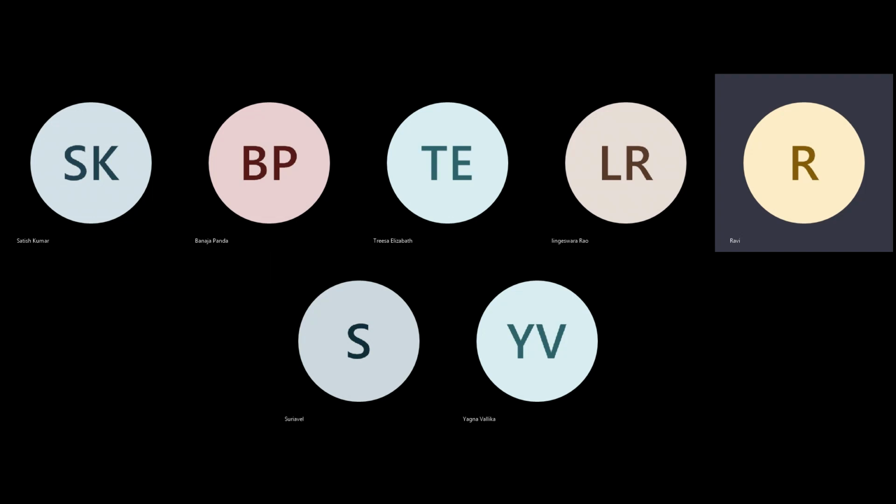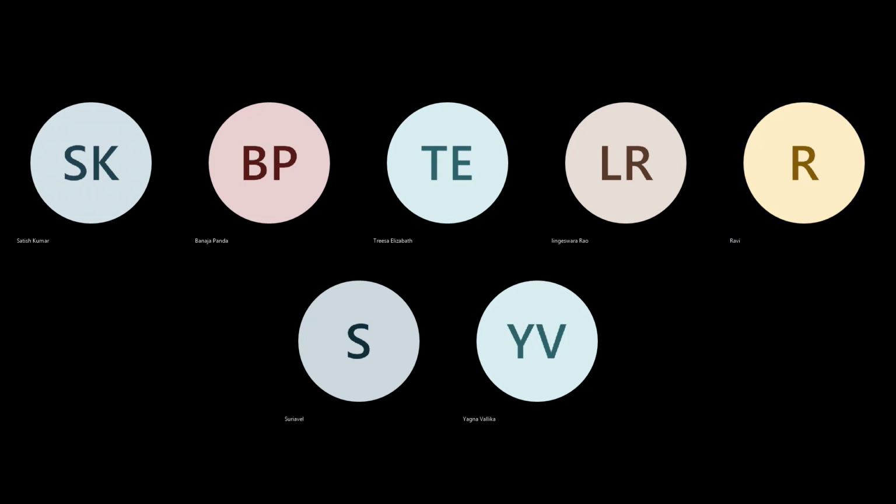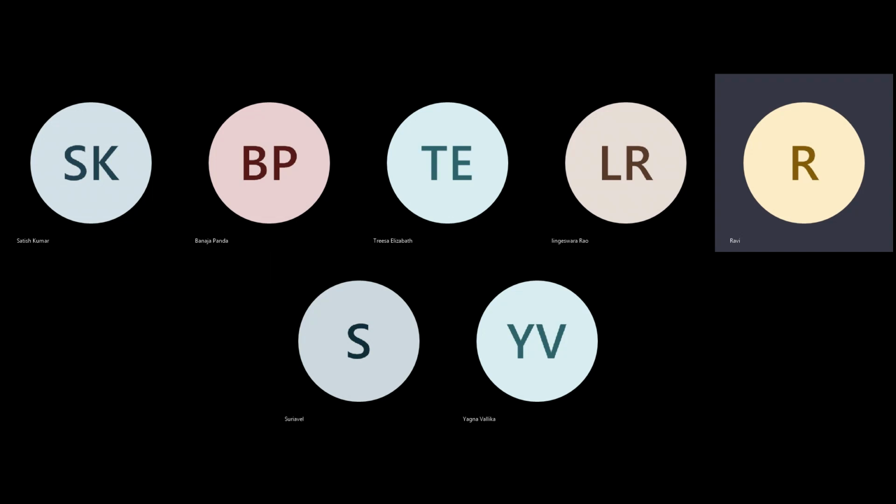But you have to know that this may be part of the same module. Inputs may have common connection. That means the same one net may be connecting to the same 4 or 8 of the D pins. Output you cannot have multi-driven. You can have one driver actually connecting to different D pins. So when you're looking at the fly lines, if all the D pins are connected, that means one net only for that. You should not multiply by 8 pins. It's like one net only. That's the net for which you have to compute.